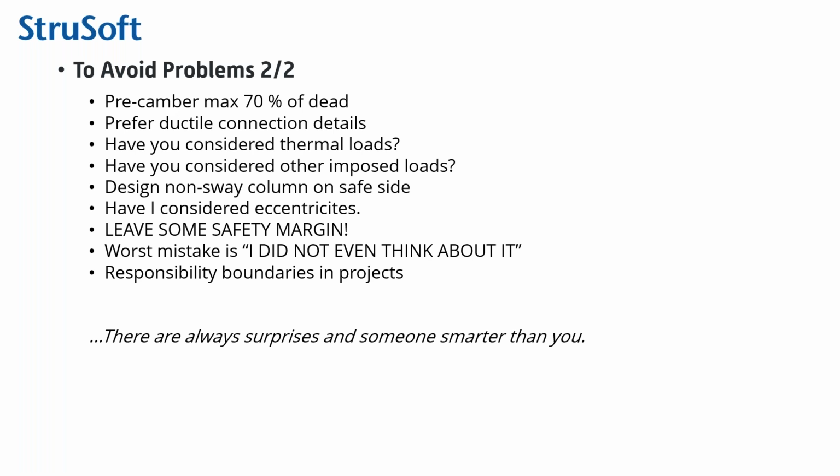Prefer ductile connections. This is out of the scope of this webinar, but it's a good idea to prefer connections where the stresses are divided evenly. Then thermal loads, which are usually forgotten in structures, but in some cases they have really high impact. Some local stresses can rise from thermal loads, and for steel it's important. And imposed loads like imposed deformation, such as foundations, are seldom done in steel structures, but in some cases they should be.